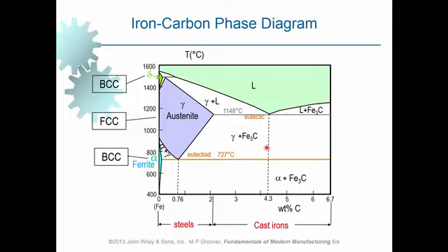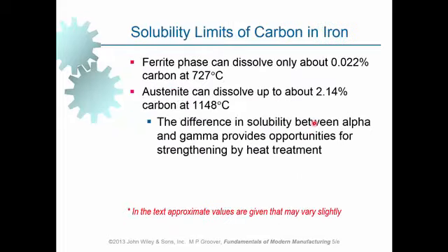Well, and in this region, if the carbon content of cast iron is exactly this much, 4.3, it is referred to as eutectic cast iron. If carbon content is within this region, starting from 2.14 to less than 4.3, then it is referred to as hypoeutectic cast iron. If it is more, what is it called then? Hypereutectic cast iron. Okay, good to know.